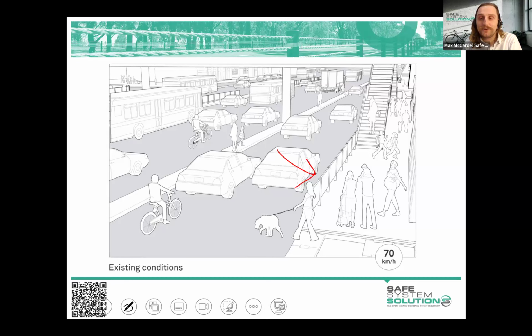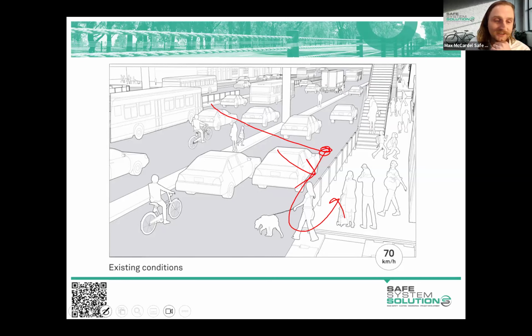And so they will jump over those fences, or what's not uncommon is to see a pedestrian get stuck on the carriageway and then go and seek that entry. So actually getting stuck on the live traffic lane, which is not a great idea. So be quite wary of just assuming that because you've got that pedestrian fencing in place, you're going to get 100% compliance with that.